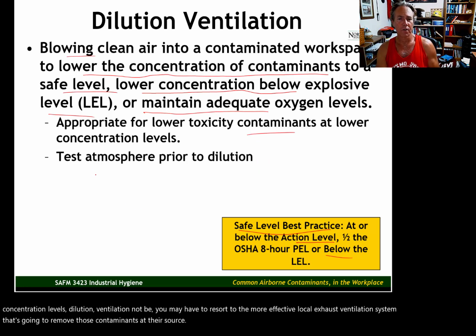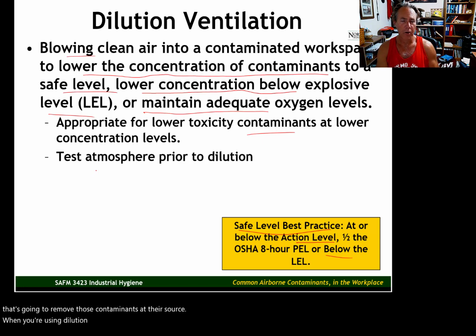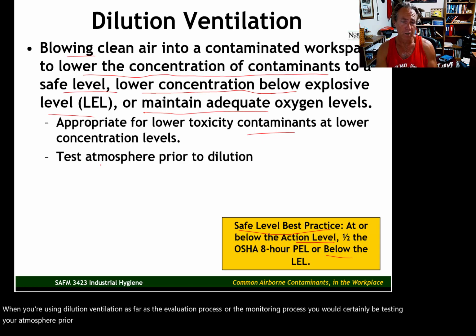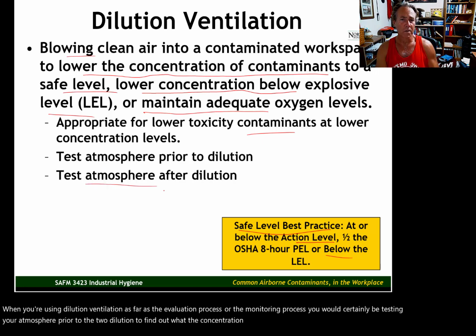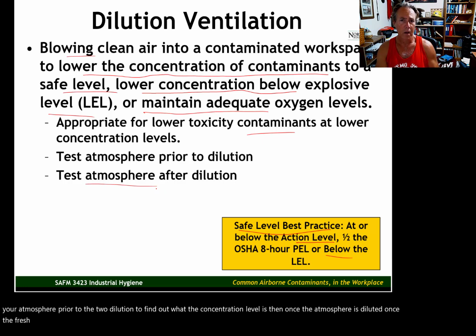When you're using dilution ventilation, as far as the evaluation process or the monitoring process, you would certainly be testing your atmosphere prior to dilution to find out what the concentration level is. Then once the atmosphere is diluted, once the fresh air is brought into the system, you're going to monitor, test again to see if your dilution air has effectively lowered the concentration.